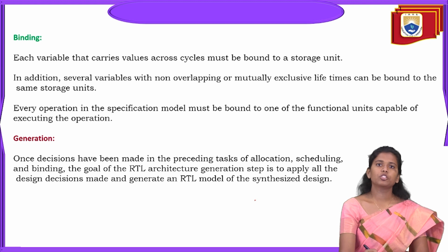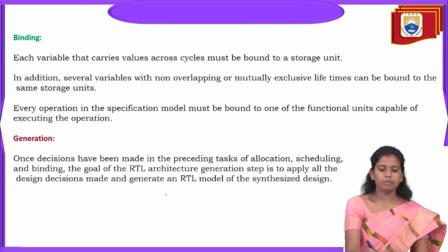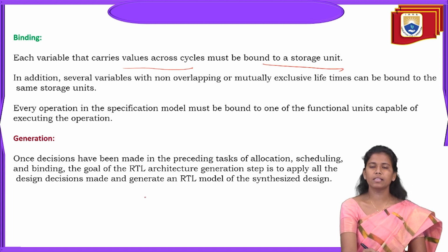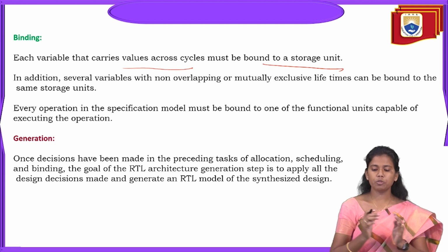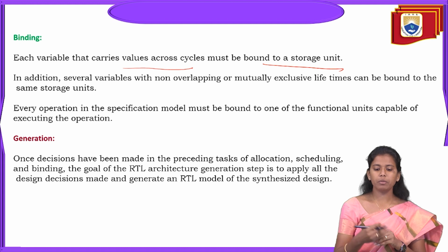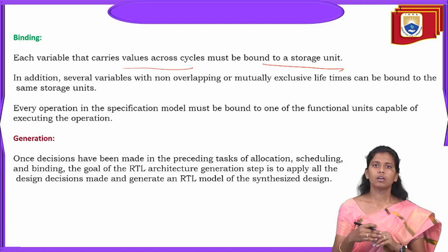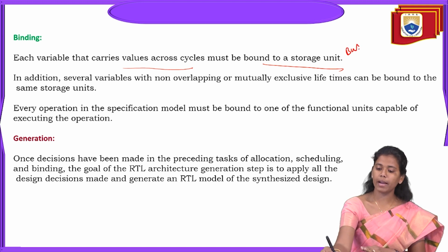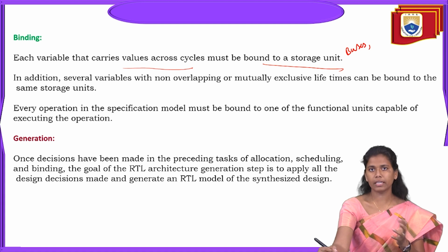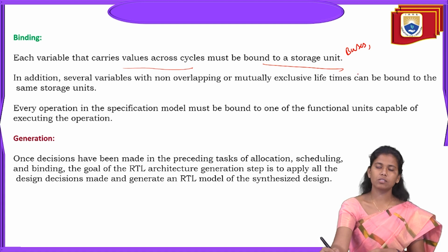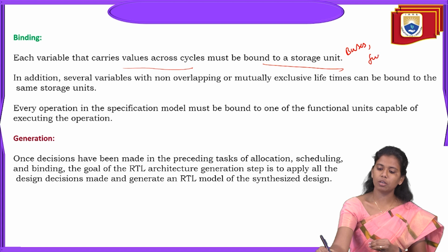Then coming to the binding. Binding is about each variable that carries values across cycles, which must be bound to a storage element. So binding is nothing but it must be bound to the storage unit. The variables which carry values as per the clock signals have to be bound to the storage elements, or else to the buses, that means the connecting devices, or else to the functional blocks.